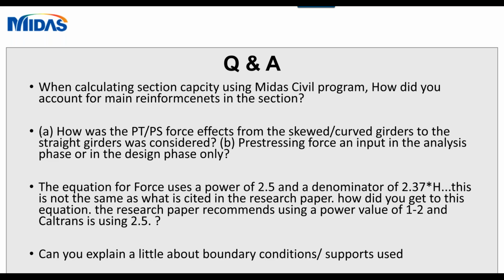Yes, the bent cap was post-tensioned. The small bent cap at the beginning was just a regular concrete cap, no post-tensioning. That's the one that is connected next to the ramp, the MSE wall ramp. But the other, the larger one that is in skew and is next to the existing bridge, that is a post-tensioned bent cap. And since the grillage was modeled, all the skew effects were considered in the analysis.